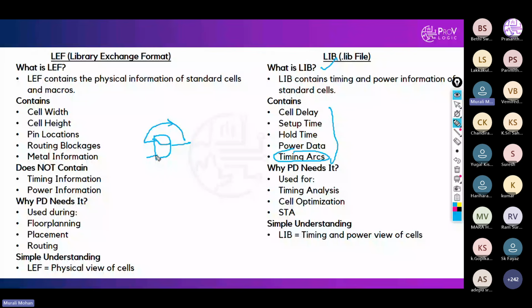Here it is done using PBA and GBA analysis. Especially this is helpful for PBA, path-based analysis, which is more accurate than GBA, where GBA gives the overall delay, like average delay, not the accurate one. PBA gives you the accurate delay for a particular path, whether it may be reg to reg or input to reg or whatever it may be.